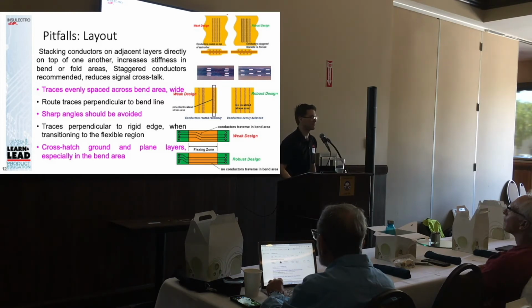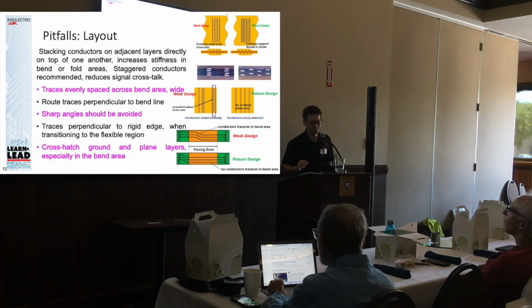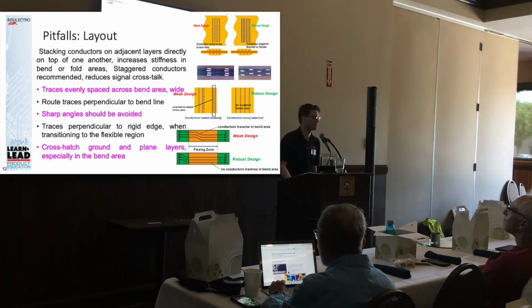Now, some astute electrical engineers out there might point out, well, this can cause crosstalk and other kinds of issues, but again, we are not moving at high enough speeds traditionally to see those kinds of issues. Jerry just gave me an eye because he's like, not anymore. We have tricks of the trade up our sleeve, but again, for most designers getting into flex, it's the basics you want to master before you get into the really intense designs.